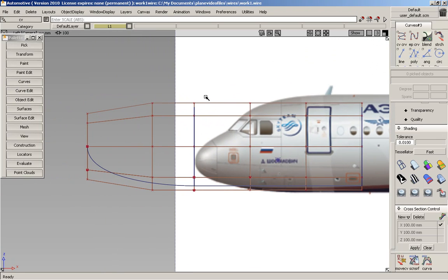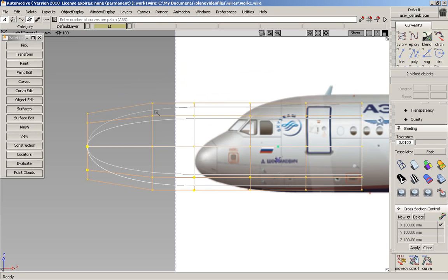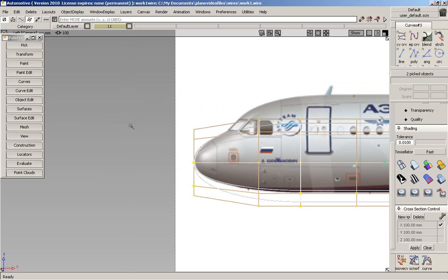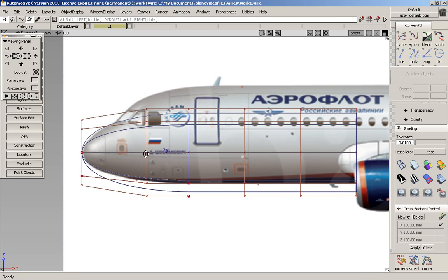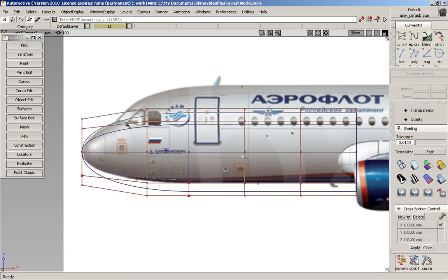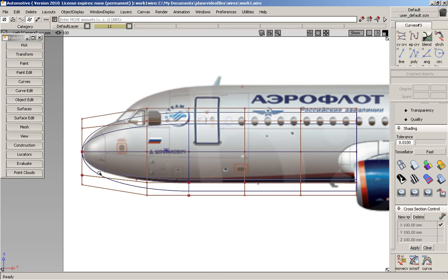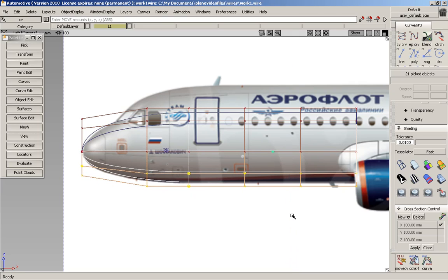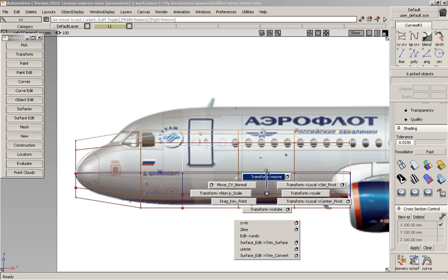So now we'll switch to a side view, and I'm just going to turn patch precision on the surface there so I can see the shape, and we'll also just move it in kind of a quick position in reference to the image. Now we're not going to show getting this exactly lined up to the reference image, but we'll get it pretty close. So just pick these CVs, bring these up so they line up on the bottom, and we'll kind of do the same on the top.